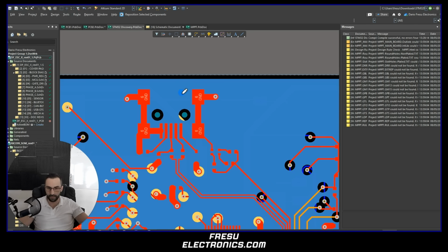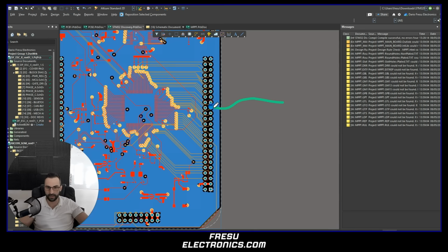The case, for example, when we have a USB, in here we want to have, first of all, ESD protections, so that we can protect the signals coming from the outside, so that we can revert as fast as possible the interference that is coming and coupling to the cable and then sneaking inside our board. For each point where we have some kind of outside connection, we want to have some sort of filtering for the signals, and we also want some kind of transient protection from the outside environment.